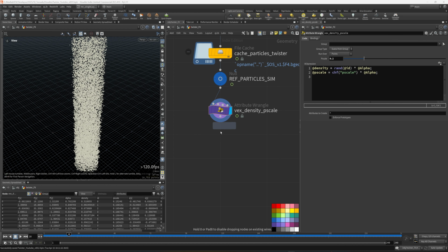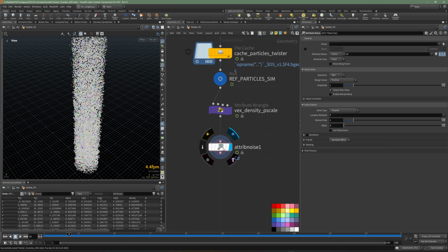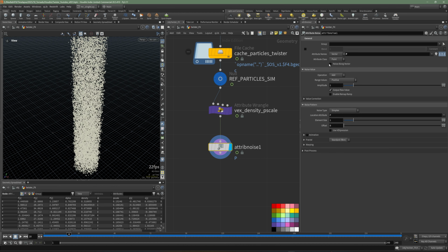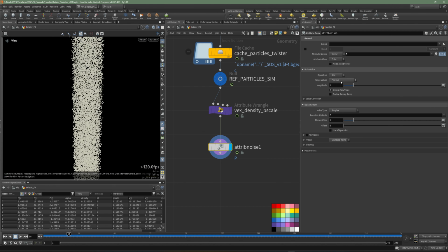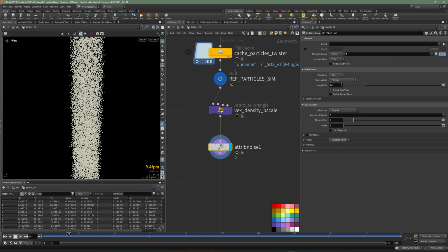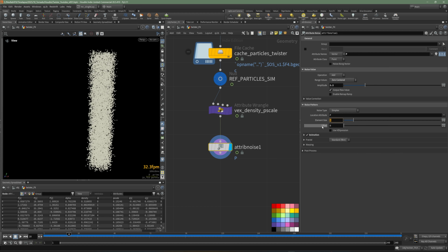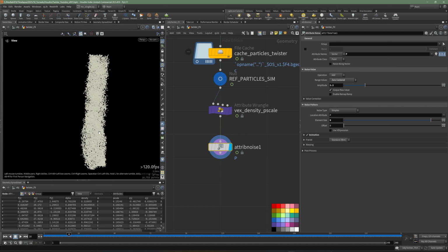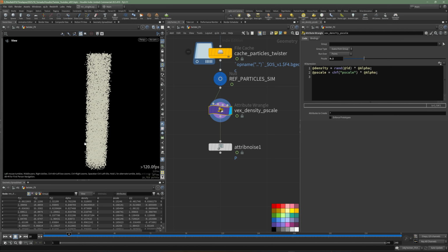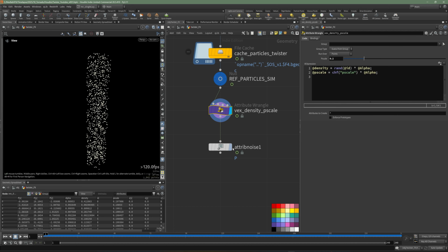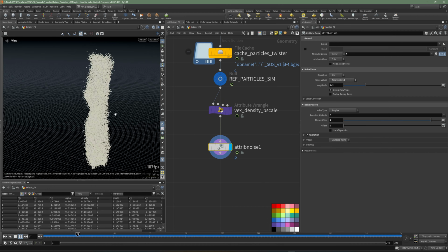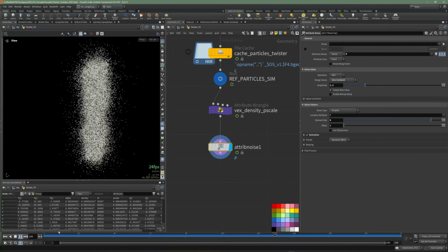Let's create some noise to deform these points' position. Vector should be P. Amplitude should be around 2.2. Range values from 0 centered. Animation and element size around 9. To avoid the static movement from these particles, let's introduce some noise, some deformation.